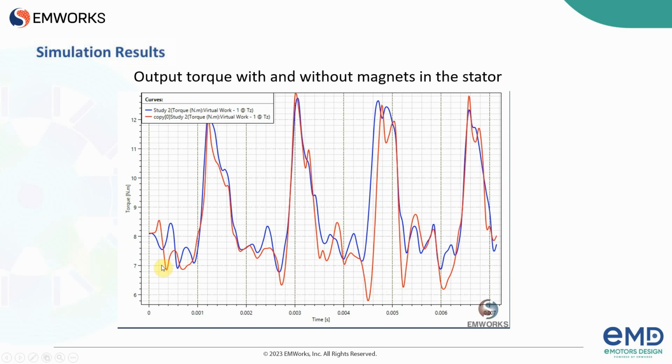If we notice, we can see the red diagram has higher torque ripple, as the distance between maximum and minimum value is higher than the PM assisted machine, and the average value of the torque is higher in the blue diagram too. So we increase the average torque and reduce the torque ripple with this enhancement.